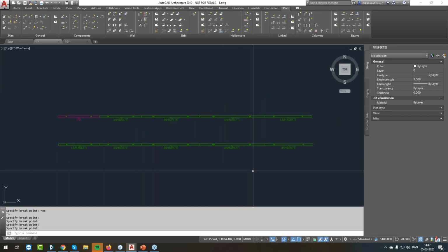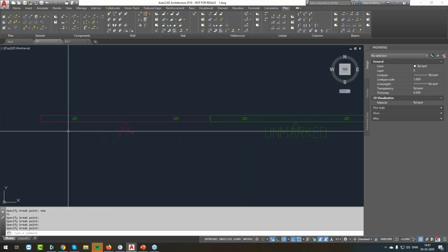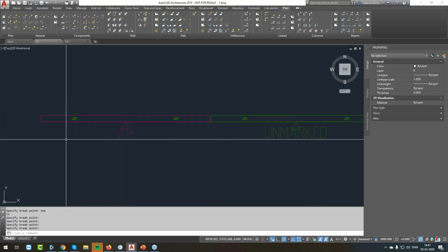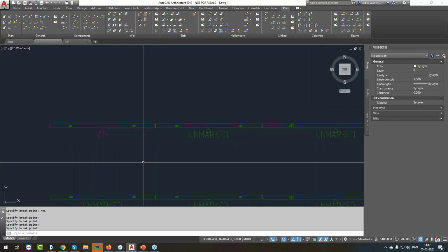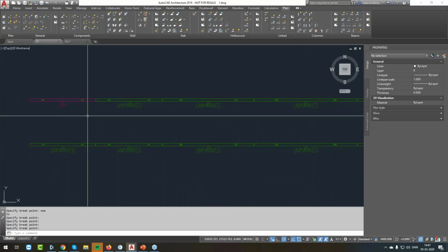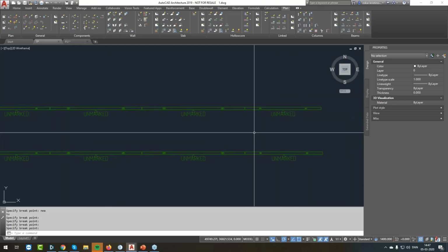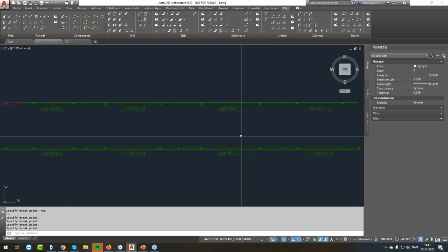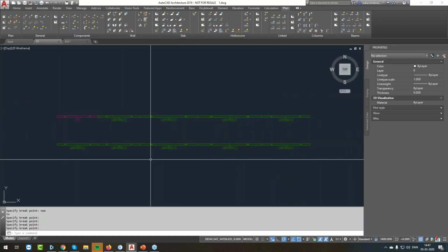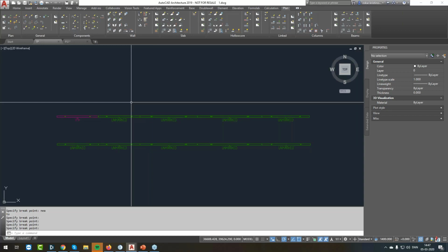As you will see, the original wall keeps its name as the first element in the wall, and you can cut the parallel walls into the same shapes, same sizes. So that saves a lot of time.